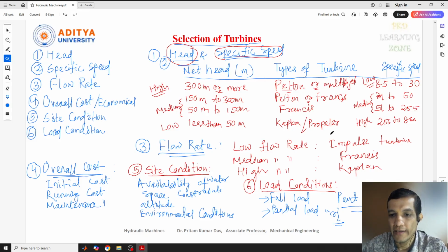And when you talk about the reaction turbine, there are cavitation formations, so in that case the efficiency may decrease. Mostly Kaplan turbine and Pelton turbine have equal efficiency at full load. Okay, that was also identified. So mostly you prefer either the Pelton turbine or the Kaplan turbine. Based on these conditions we select this.